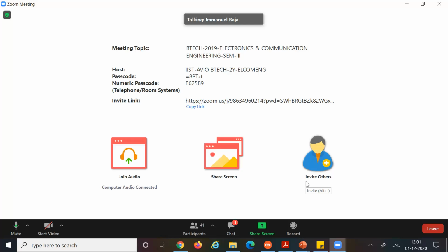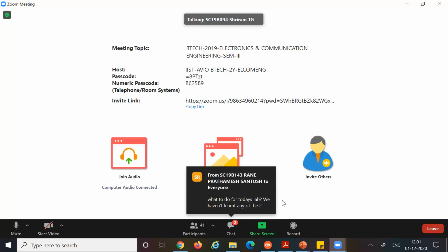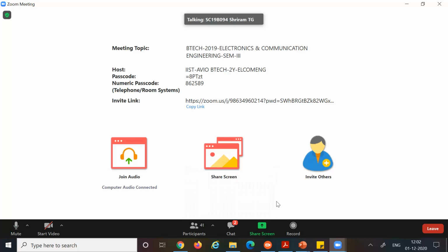How are you simulating a BJT in LTspice? Are you taking an existing BJT? Some of us are using the beta values from the lab with a standard NPN transistor. But some of us are downloading the model of BC107 and changing the beta value. Okay. For all transistor-related experiments, you can just take the beta to be 200 for the lab exam.